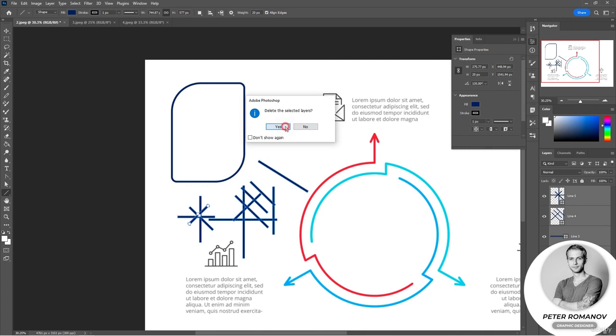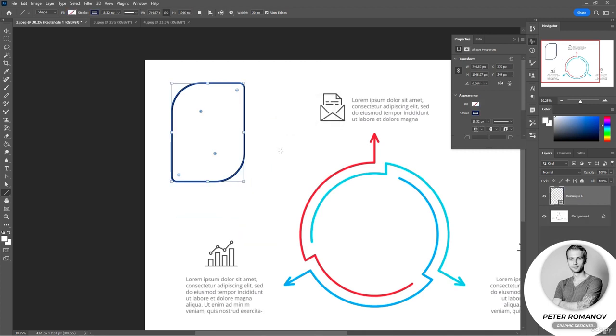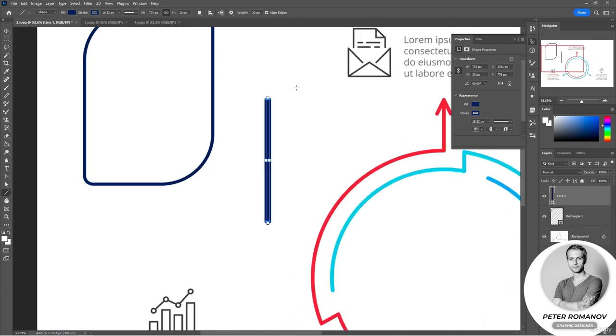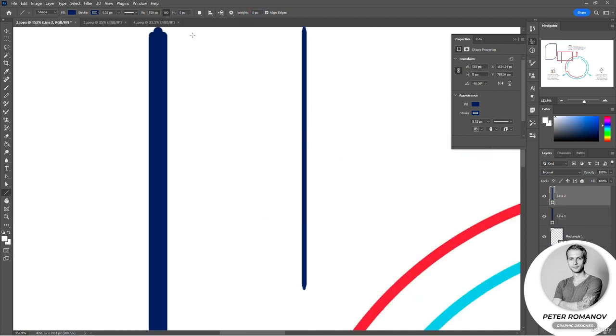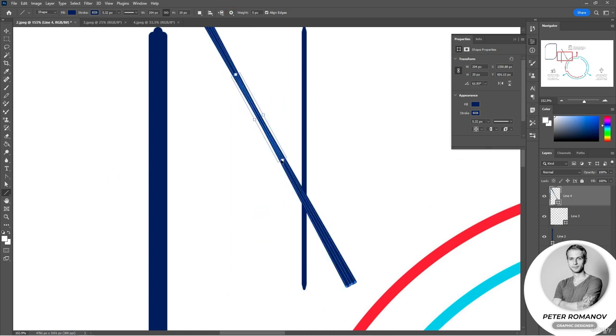So I'm going to delete all these lines that we have drawn. And let's see how we can make an arrow out of them. To do this, we click on the gear. And look, here you can set whether the arrow will be at the beginning of drawing, or maybe both at the beginning and at the end. Well, for example, I set both at the beginning and at the end, and then I draw an arrow, and I get it like this. Also in the same menu, you can change the shape of the arrow tip. And look how its tip has changed.